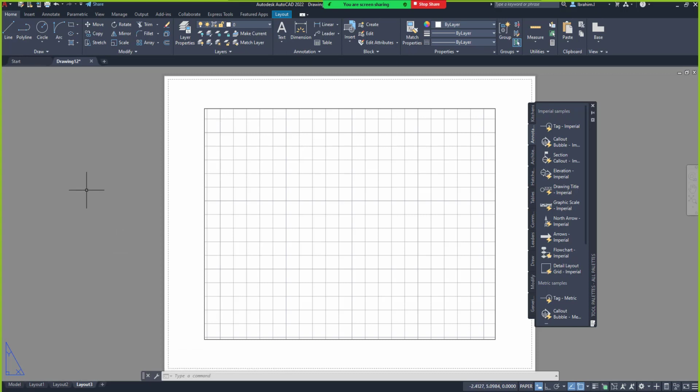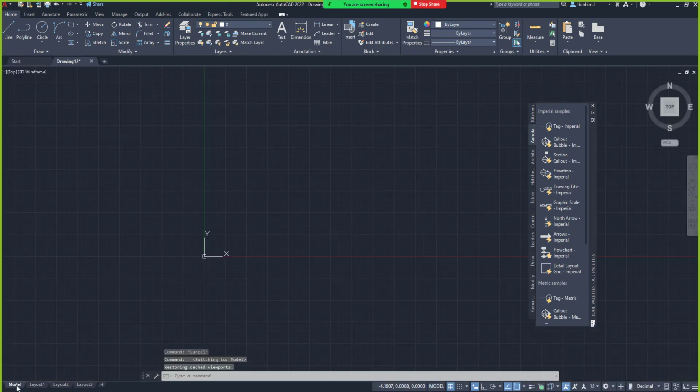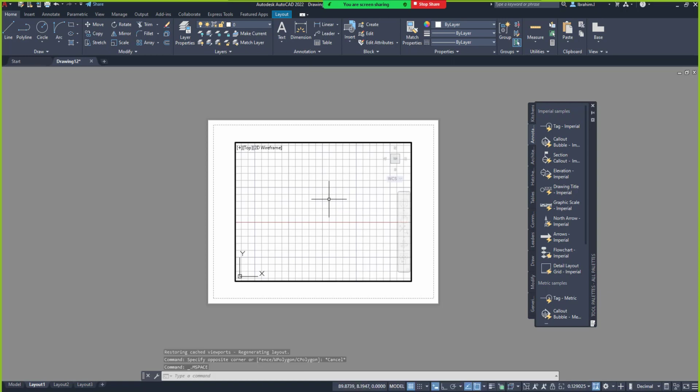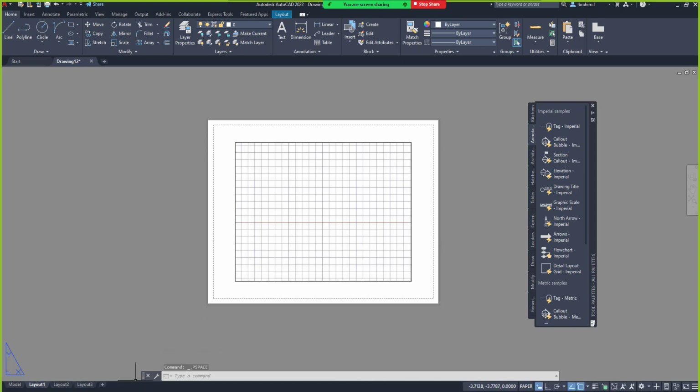So if I'm printing, or plotting, I have to go on the layout for me to print, to print the design out. Yes, that's what we are talking about now. That means you must have designed something on the model space, right? So after designing on the model space, you go to your layout, and then you adjust to that drawing that you've worked on, and then you start exporting out as your print. We'll get there. We are going to export a drawing out for ourselves.